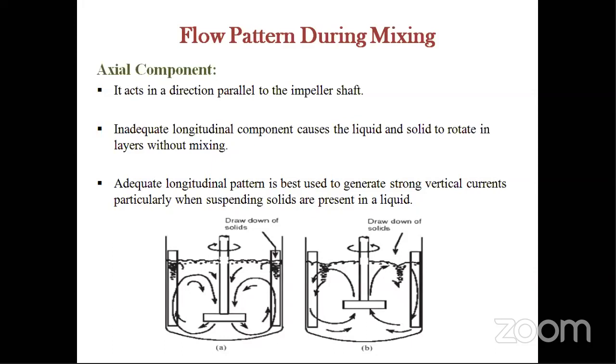The axial force or flow pattern again lifts the solid particles which had settled at the bottom of the tank, and they are mixed with the liquid materials again. So every time, the solid particles are kept suspended in the liquid. This happens only when you are going to mix solid and liquid material in a mixing process.